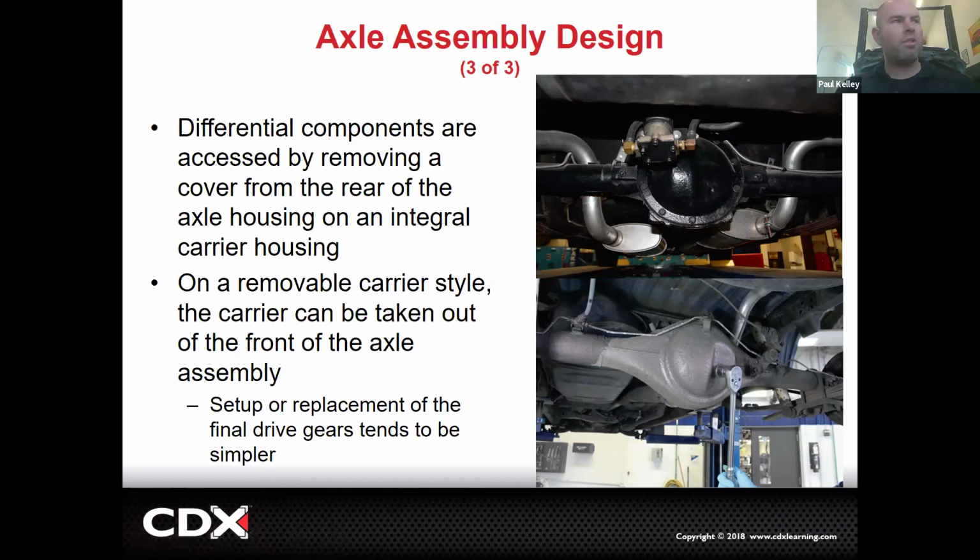This always had a plug. Cool. So let's say if you look at this one with the cover, you guys can see the cover's bolted on. If you needed to do differential service on this, you're unbolting this cover and you're standing under the car and you're working on the diff right here. Whereas this one, you could actually pull that whole carrier out and go build it on the bench. That's why this looks welded up right here, because you don't access it from the back. You pull the whole carrier out and go work on it. Cool. That's kind of one of the big differences. And that's what this one's saying. On a removable carrier, you could take it out. It's pretty nice.